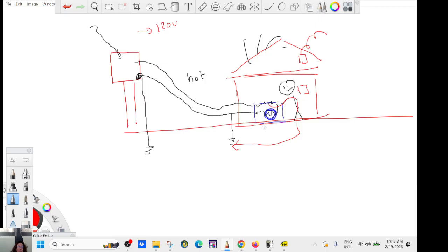So that's why now those devices, they have another connection straight to the ground. So that way, if there is some leakage, maybe it will go through you a little bit, but some of it will also go through the ground here for security. Yes. So it's always taking the path of least resistance. So you don't want to be that path. So it's advisable when you are doing your machine, especially in Florida when they take so little care of the machine. You don't want to do it in flip-flop, right? Your bare feet, even worse. You never know.